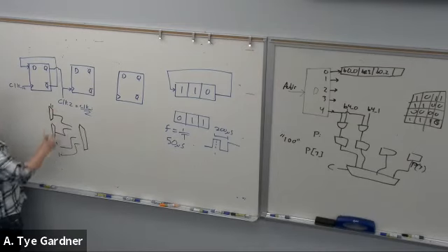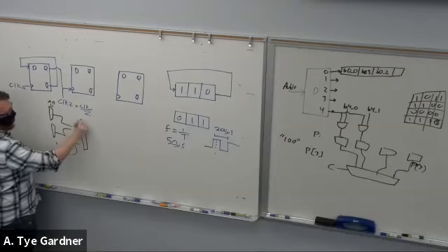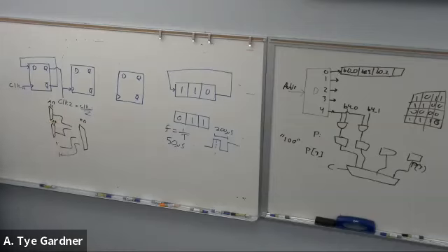Each of those has to have 2 input control signals. These 2 share, this first column shows 2 of them, the last column has 2 of itself. So the inputs are A, B, C, D, and A and B are your selection signals. Then you have to make sure your selection signals are the right 2, more or less. And you can always check that by saying, well, if I give it 0, 0, 1, 0, do I get that node?